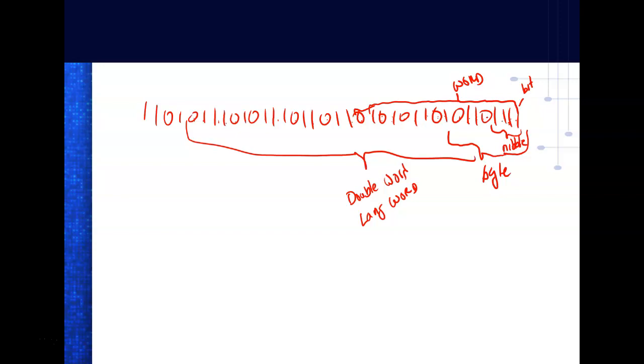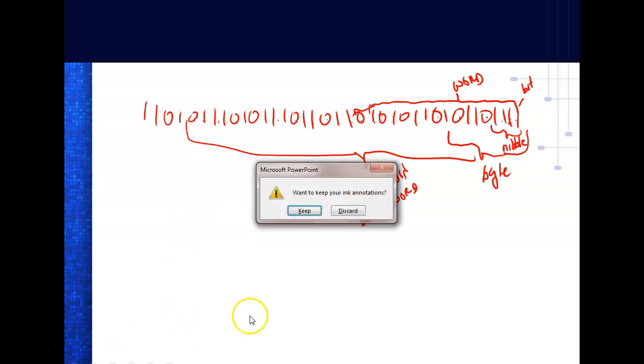So we're okay. Allen-Bradley deals with words. Siemens deals with bytes, and that's one of the big differences when we get into a Siemens PLC, because we get used to dealing with these 16-bit storage locations, and then we get into the Siemens, and they go back to bytes. But you can still access information in bytes, words, double words, long words and double long words.